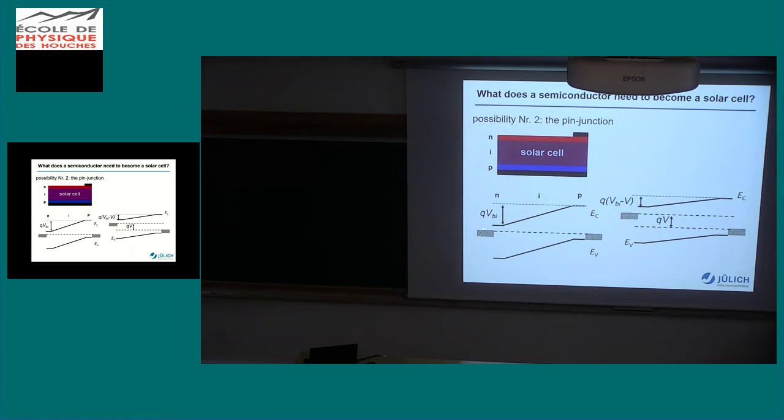And this is why you make the space charge region so large, almost the entire solar cell, and then every electron, very slowly moving, at least instantaneously knows in which direction to go, and has not to diffuse around to check the one boundary and check the other and find out that on that contact I can get out more easily than on the others. That was a PN. Here it is immediately more or less clear. So, but what happens here then if we have, say, a little help from that field? Done?